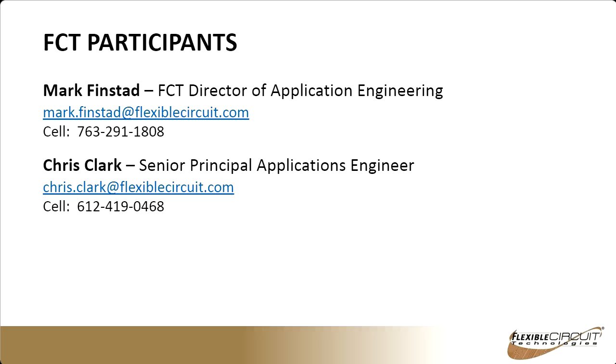What variables need to be taken into consideration when figuring out what wattage is needed? Probably the big one there, as Mark had talked about, is just the environment that it's going to be used in. What's the operating temperature? What's your heat sink material? Is there a fan or a breeze going to be blowing on it? Those are all things you're going to want to take into consideration.